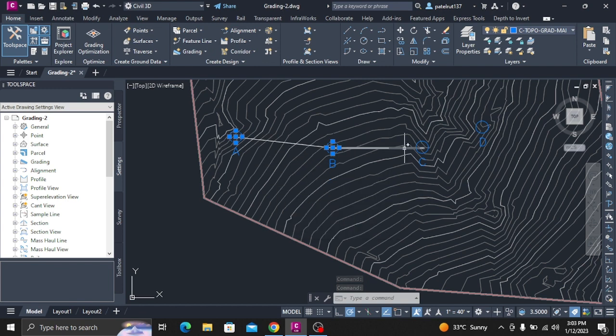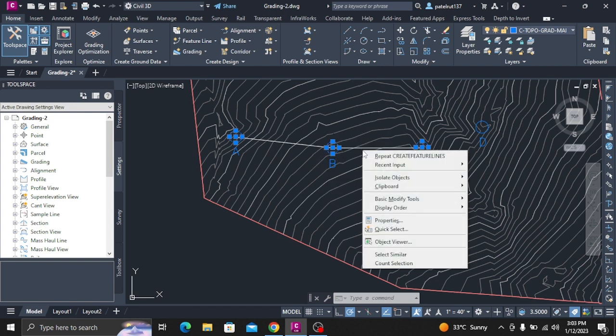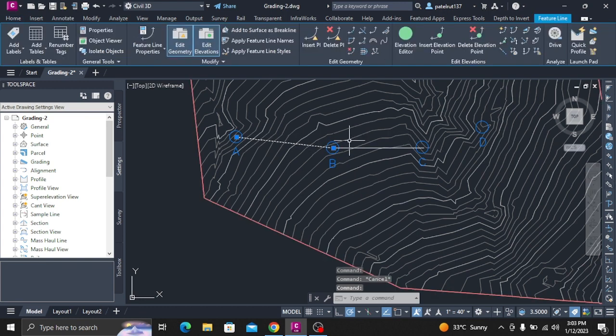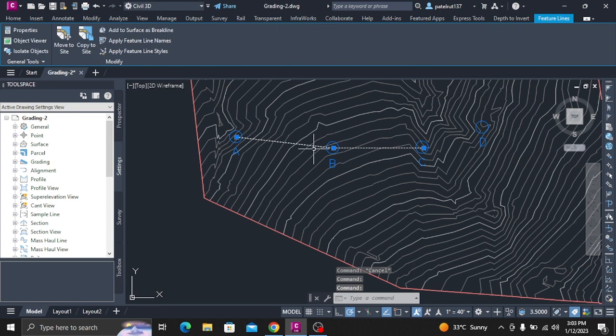In the drawing window, snap to the end of the feature line inside Circle C. When prompted, enter 688.00 as the elevation. You have entered a known value for the starting elevation. In the following steps, you will use the transition command to defer entering elevation values at intermediate points along the feature line. Stretch the feature line and click inside Circle D.